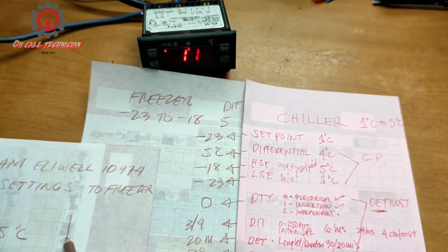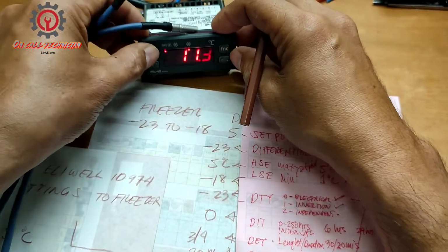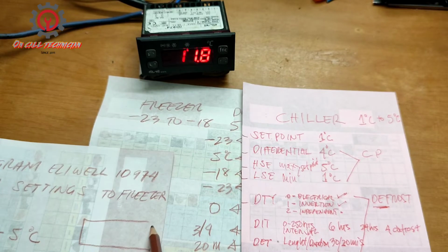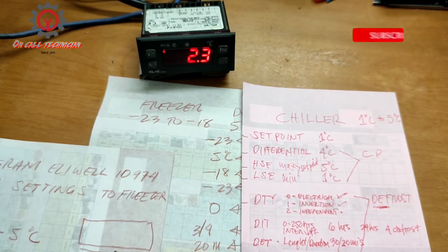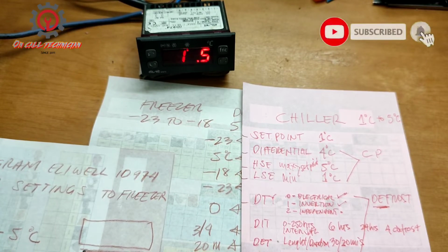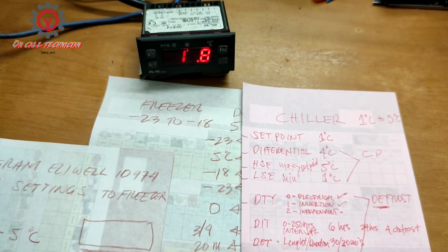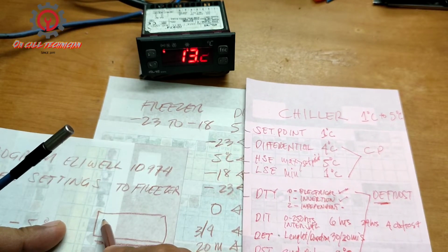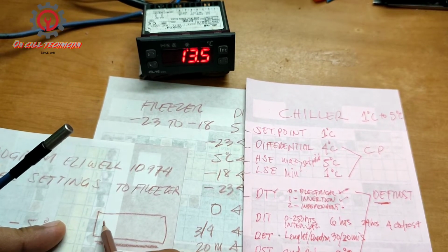For example, this is your evaporator, and the defrost heater is under here. This defrost heater, and usually the sensor, we install the sensor on the back part. Okay, we just insert it here on the back.